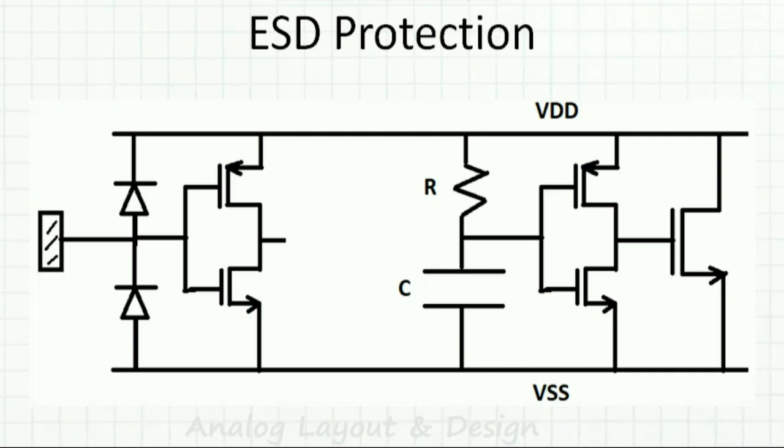Now we will look into the overall big picture. Whenever a pad voltage goes high, from 0 to say 5.6 volts, here it will be 5.6 volts only, and this node voltage will be around 5 volts. So what happens to this discharge? All the charges will come here, this node voltage will be 5 volts, and it will go here, and you will get a discharge path.